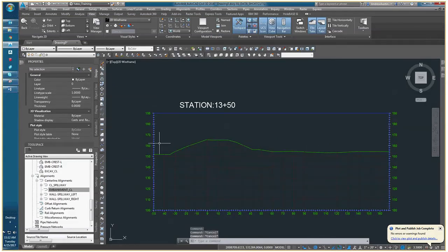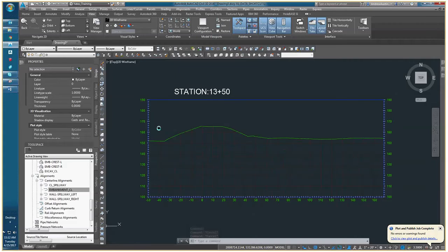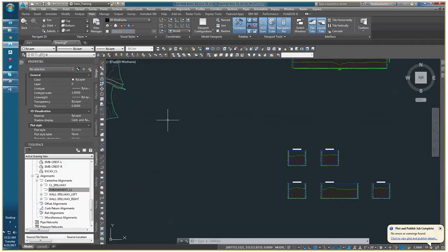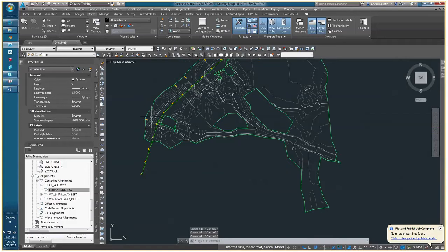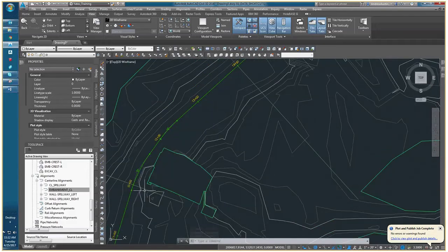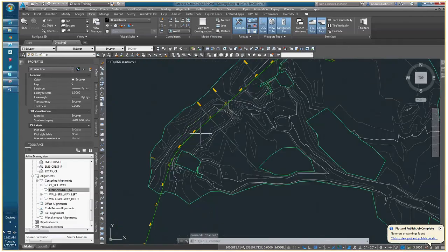In other words, the reservoir is on the left-hand side, and our downstream tailwater area is on the right side of that section. That's exactly how we wanted to show it, and that's entirely driven by the alignment direction. So our alignment direction is a pretty critical component of our eventual layout of some of these elements.